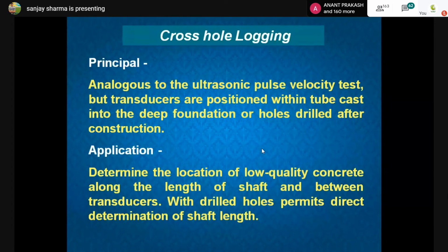This is cross-hole logging. This is very similar to ultrasonic. The only thing is that we have to provide holes in the foundation, which are drilled after the construction. So there we can locate the low quality concrete with the help of this.